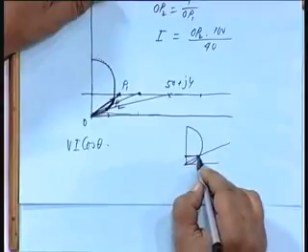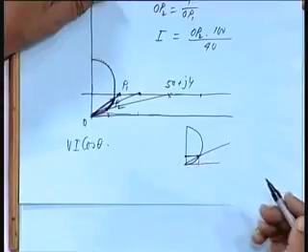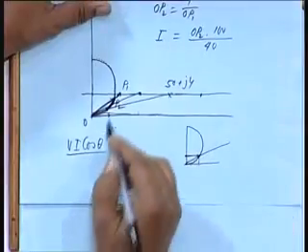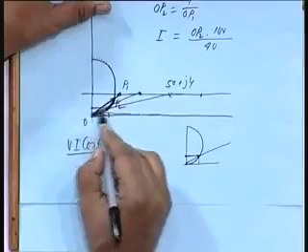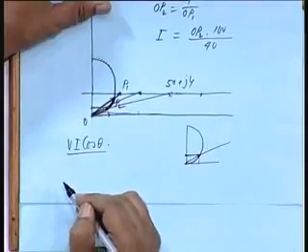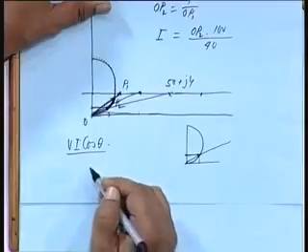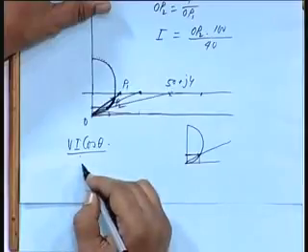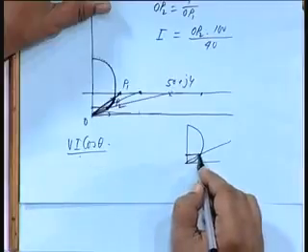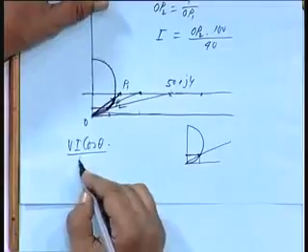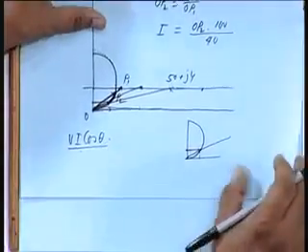So, measure of this distance multiplied by voltage 100, is that all right? So, Vi cos theta will be the horizontal segment of that point on the semicircle multiplied by V 100, of course, that divided by 40 scale factor. What I am measuring as I is actually 40 times I. So, you have to take that into account.